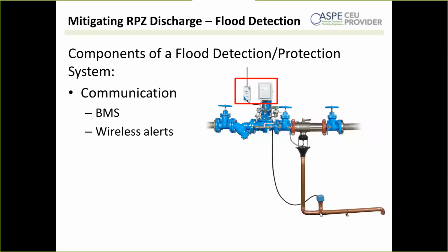It doesn't have to be every day necessarily, right? It depends on how dirty your water is. But just periodically, once a week, something like that, you're going down, you have gauges installed directly upstream and downstream of that strainer, just check your head loss, write it down somewhere, and once it starts creeping up, right, you should be able to kind of see a general trend. Go ahead and schedule some routine service.